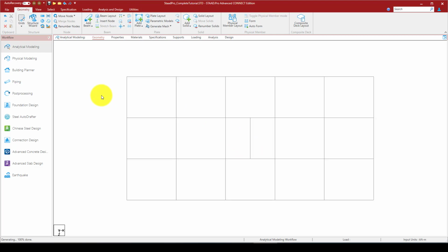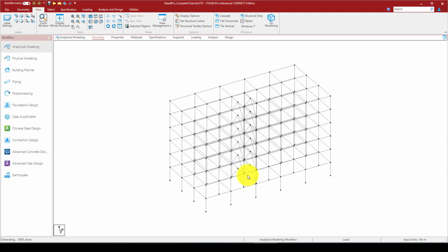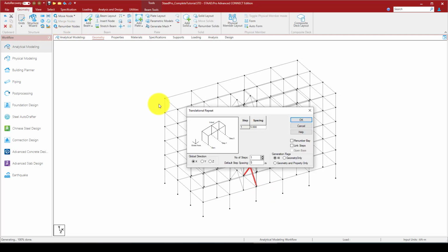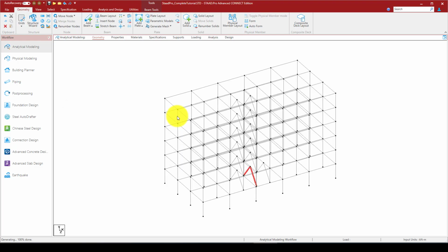One more thing: I'm going to go to the 3D again, and in the 3D I can select just these 2 braces. After that I'm using the same geometry here and the same X, and it's going to be 3 meters. But if I use this one, they will create an extra and break together. So let me first do it to see how it looks. If I select this one, now it breaks, it is not correct, so I want to use this one.